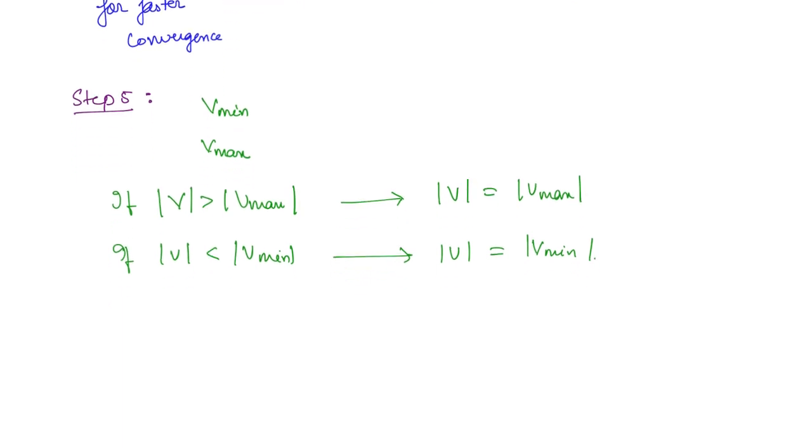So this is step 5. You have to repeat steps 4 and 5 for all of the PQ buses. So that means, let us say for the second bus you are finding the voltage, then you will do step 4 for the second bus and you will check the limits, that is step 5, and then you will go to bus 3. If it is a PQ bus, then you will again do step 4, then step 5. So you have to continue like that for all the PQ buses.